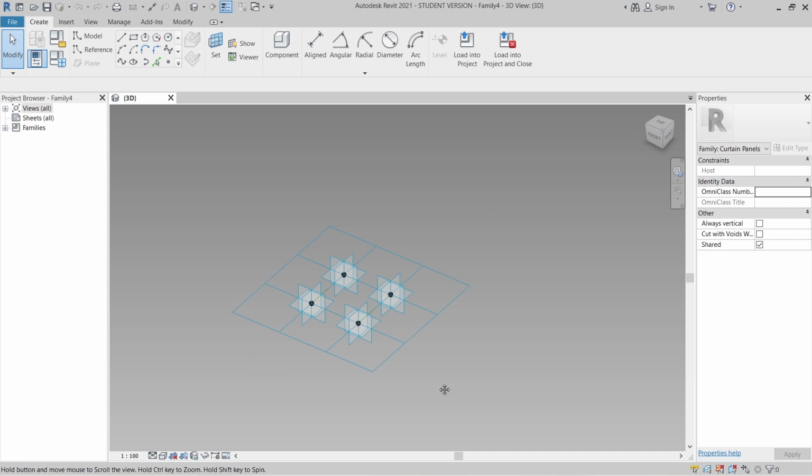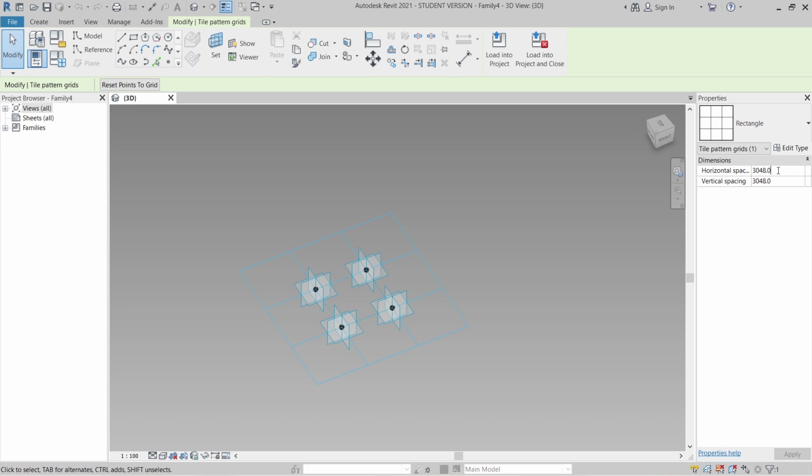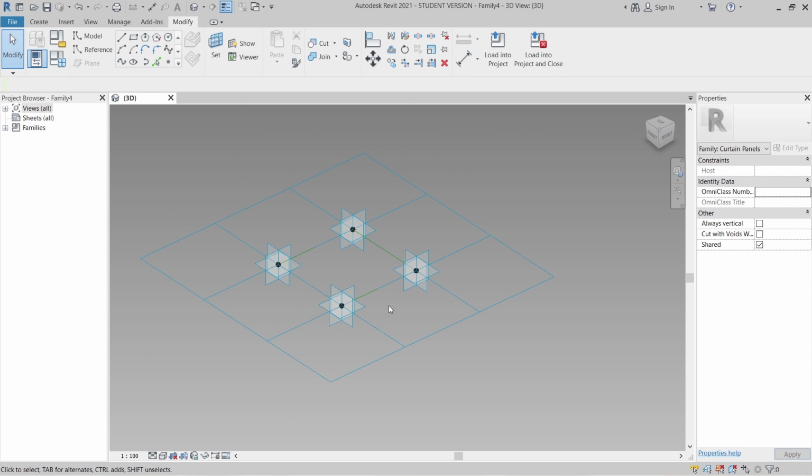Okay, so now here is just a normal panel. What I need to do first is select my panel here. Then I want to give it an accurate size of 3 meters by 3 meters, which is easier for us as a square one. Okay, now let's place our reference points to create our pole and our wire mesh texture.